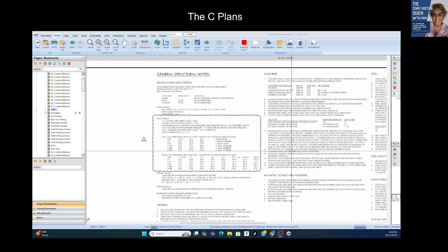Okay, so first we have the top of the building and the roof framing. That's where the load starts. It starts at the roof, right? The roof deck, the trusses. And those things are carried by what? They're carried by beams. So think of going from the top of a building down to its foundation. That's the load path, the vertical load path we're talking about.